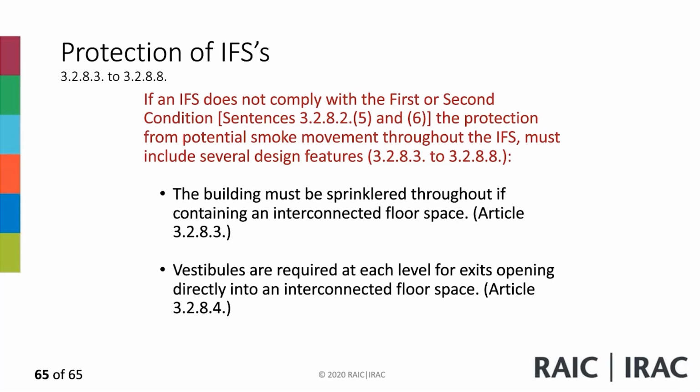And there's specification for the vestibules. If you're looking at 3.2.8.4, you'll see that the vestibules have doorways not less than 1.8 meters apart. They are separated by fire separation from the floor area, but they are not required to have a fire resistance rating, and they are designed to limit the passage of smoke. So you need to have pressurized, basically, vestibules.